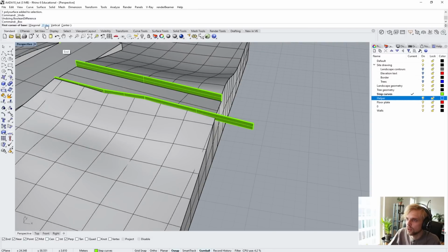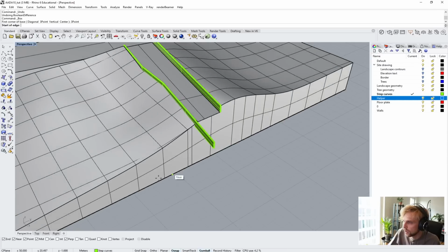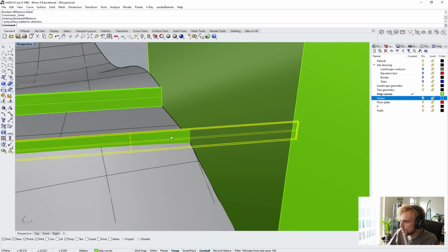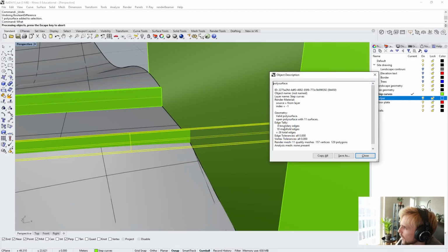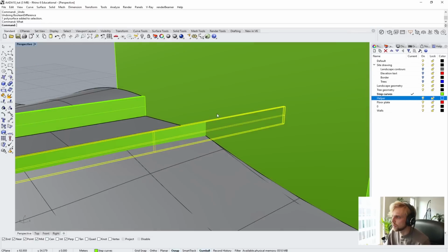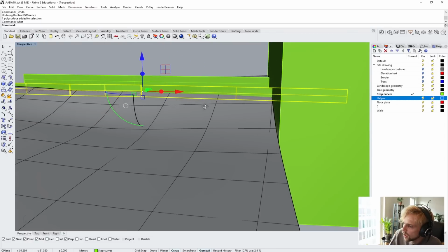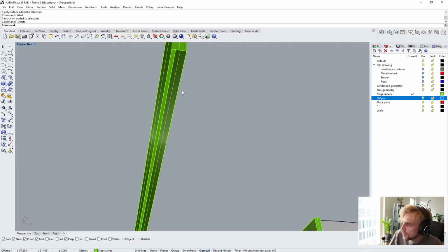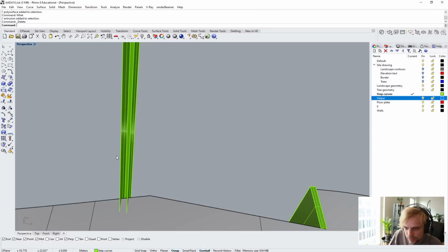So I'll just create a box with 3 points, right? So the box is going to follow an edge here, and extend pretty high. And then boolean difference from this with the box. Shit, still kind of makes a mistake there. Okay, let's see. Open polysurface. Okay, so it's open. Why? Oh, I know. For some reason, when we use extrude surface, it forgets the bottom.